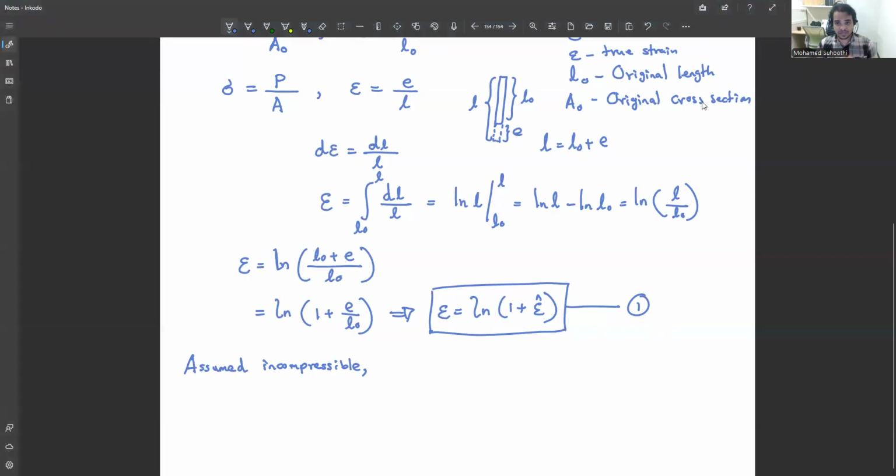Why I am saying this is important: I have seen many research papers in finite element studies that did the finite element study for compressible cases, but did the Abaqus analysis using the relationship I am going to derive now, which assumes incompressibility. But they are doing the research for compressible cases. It is completely rubbish. There are many such papers. Even the high research community doesn't consider this part carefully.